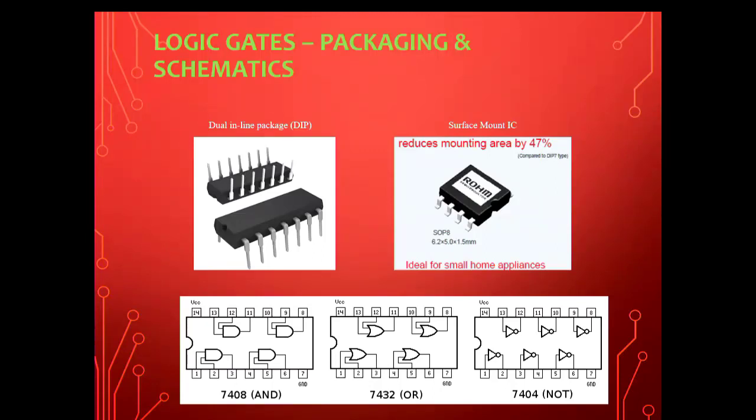And they come in different packaging these days. This is what we refer to as a dual inline package. This is a 14-pin chip. If you look at this notch, usually this is pin 1, this is pin 7, 8, and this is pin number 14.